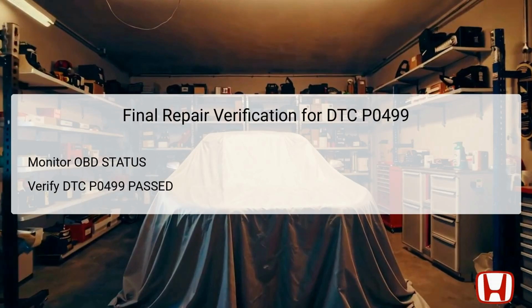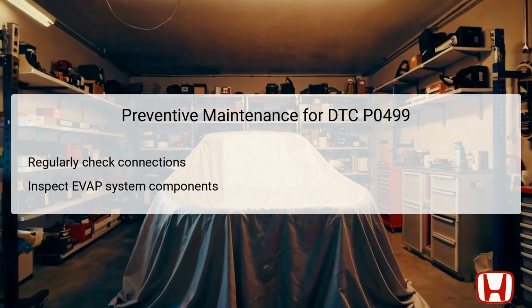other potential faults. To prevent the recurrence of DTC P0499, it's essential to undertake regular preventive maintenance on the EVAP system and its components. Start by frequently checking all electrical connections associated with the EVAP canister vent shut valve and the PCM. Keeping these connections free from corrosion and ensuring that they are not loose will significantly reduce the risk of encountering high voltage issues.